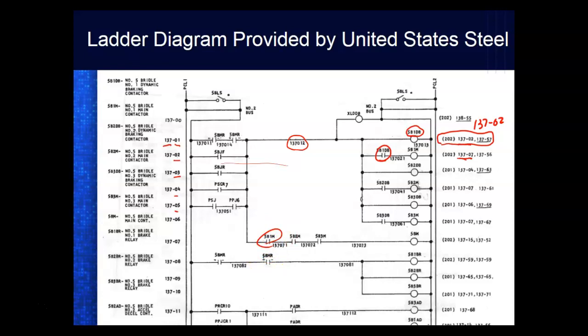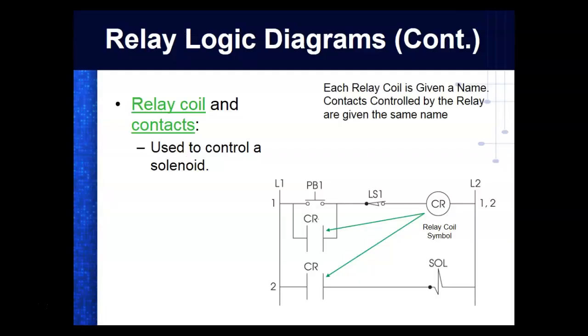So instead of me trying to draw lines like I did back over here, showing you these contacts, we give the line a number, right? So this is wrong over here. This shouldn't be like this. This should be 1. That should be 2. And that right there should be 3. And then we'd come over here. So every horizontal line gets a number. What the book does is number rungs and not lines, right? You understand? So this is where the book is wrong. And then over here I would have 2, and I have 2, and then I have comma 3. So this came out of the book. And you need to know that because you're going to get into motor control.